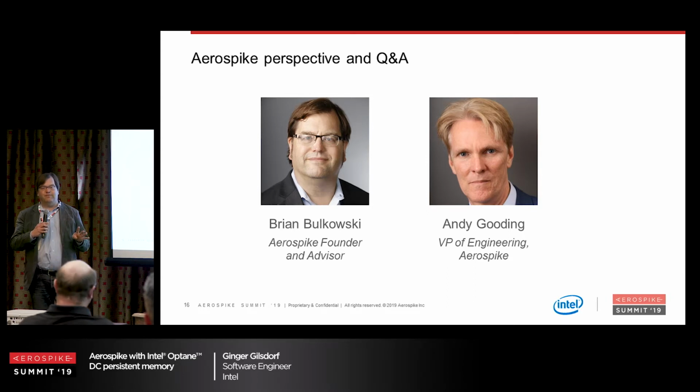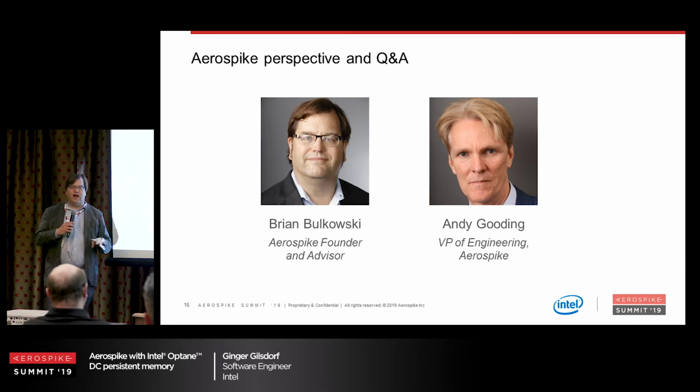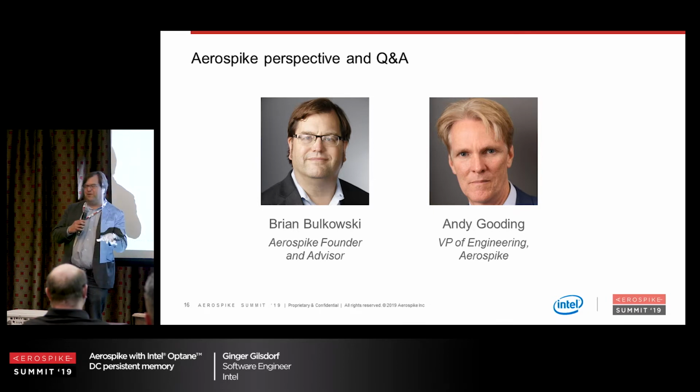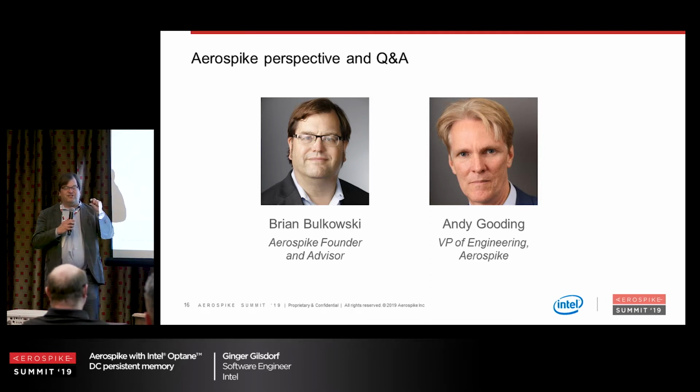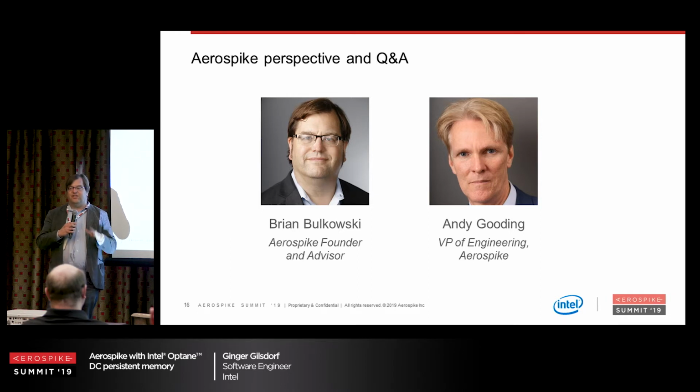There's now a fourth way. And the general idea of, I don't know if you're calling it phase change memory. She's not allowed to call it phase change memory. Go look at the Wikipedia page. But basically you take a little piece of a substance, you melt it, and then when you cool it, if it cools slowly, it forms a crystal, and if it cools fast it's an amorphous solid. And those two have two different resistive properties, and then you can just go read the resistance. That is the general concept.